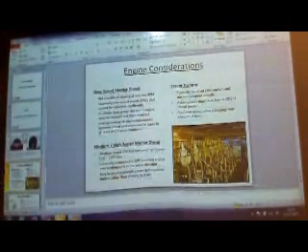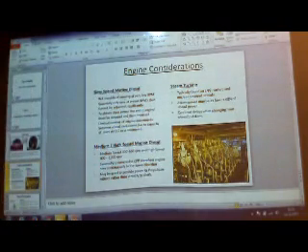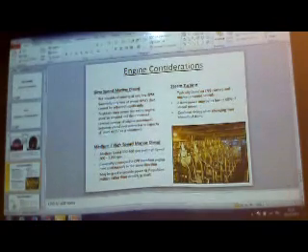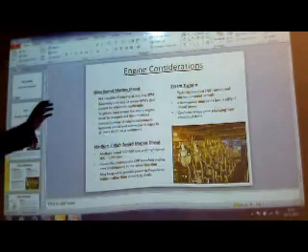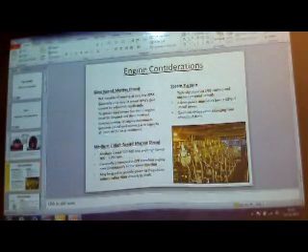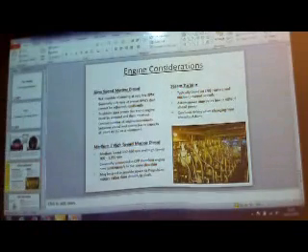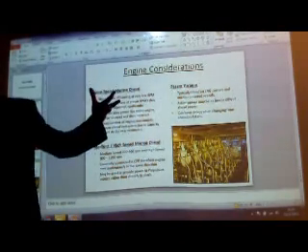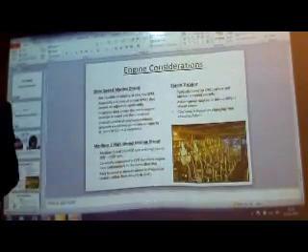Well, a ship, if it is designed to move from one part of the continent to another part of the continent, are you going to keep on moving it again and again? No, you will achieve one steady speed, and you want that ship to continue on that steady speed for the better part of its voyage. So for that kind of ship, a bigger engine, a slow speed engine with lesser RPM and higher efficiency is required. You are not going to gain any higher efficiency by increasing the RPMs, pumping in more fuel and increasing the revs, are you? No. So you would want something big, slow and steady that can keep on running at the same pace slowly forever and ever, don't you?